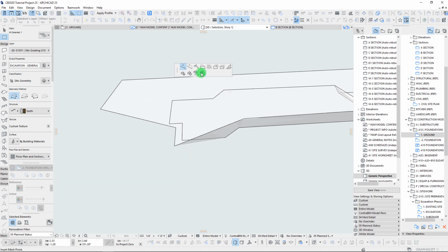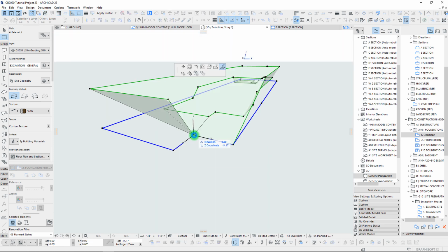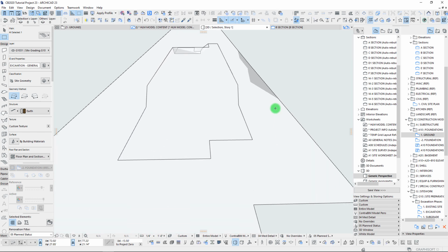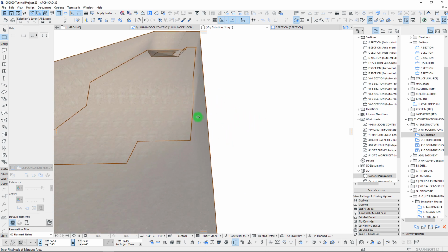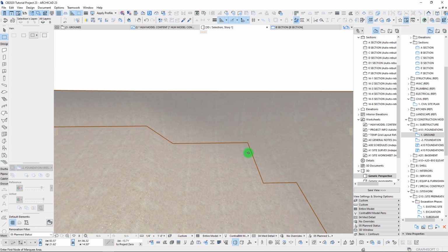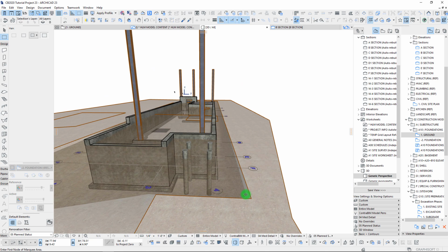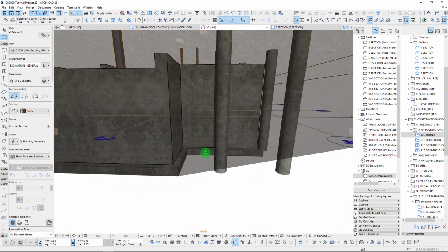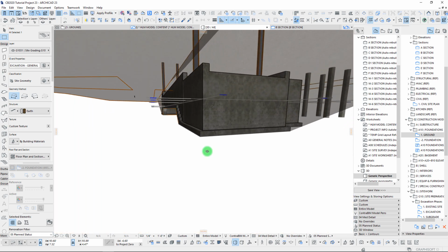So we got some work we need to do over here. Certainly we can offset these, offset this back a ways so we can slope. This will need to come up. And okay, so we're starting to get that shape coming through. Where we got a bit of a challenge is going to be right along this point here, because that's where our property line is. So that's where we talked about before, might having to do some shoring right here. Because this is a really steep slope, I think we'll probably have to add that in. But right now we are starting to get things working.